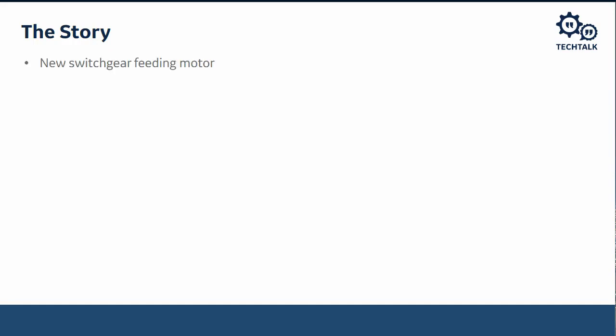Switchgear is feeding motors. So these are medium voltage motors. They're pretty big motors, and they don't switch them very often, so they're feeding them with switchgear rather than a motor control center. Not unheard of. When they start the motor, it trips after about 10 minutes. Now, it's a whole switchgear lineup with multiple motors being fed by the switchgear lineup.